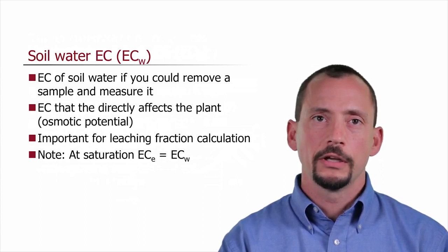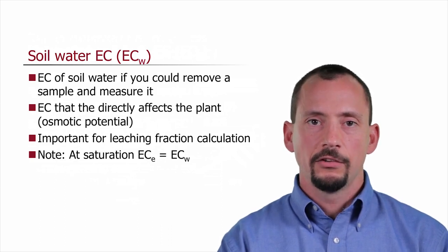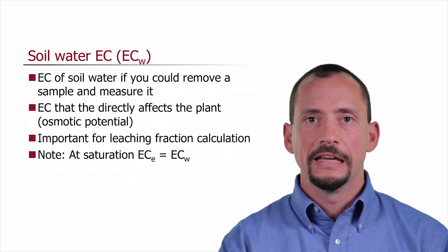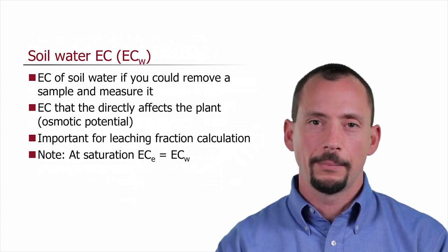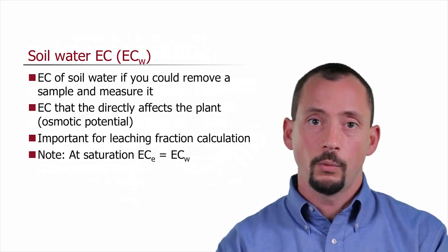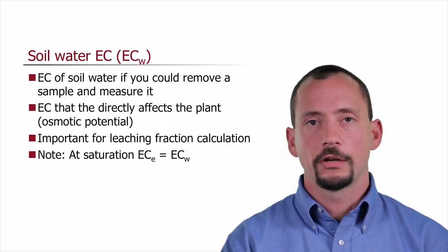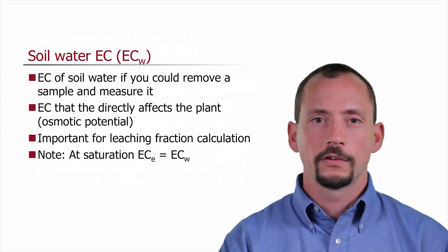And then again, a note that at saturation, of course, the saturation extract EC is the same as the soil water EC. Remember, we're just pulling a sample out at whatever water content level, but if we're at saturation, the sample we pull out is the saturation extract EC. So only at saturation are those 2 things the same.